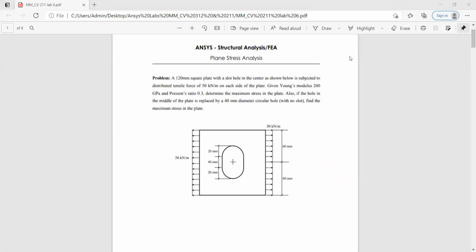Okay, Payal's asking, in the lab write-up format, there is a part saying modeling and/or design. What are we supposed to do or show under that section? Okay, so modeling and design is when we are basically defining the geometry. So we drew our beam, and then we applied the mesh. So that's the modeling section. And you may also talk about the boundary conditions that we apply. Boundary conditions are also known as restraints. Are you all clear as to what I mean when I say restraints?